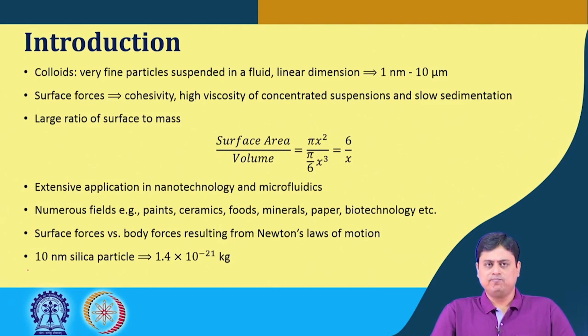Now, these fine particles we will be using interchangeably here as the fine particles, and when these are suspended in liquid, they are the colloids. Now, in this case what becomes a critical factor is the surface forces, because these small particles, if we look at their mass, are of very small amount of mass. Now, these surface forces are the reason for fine particles being cohesive in nature.